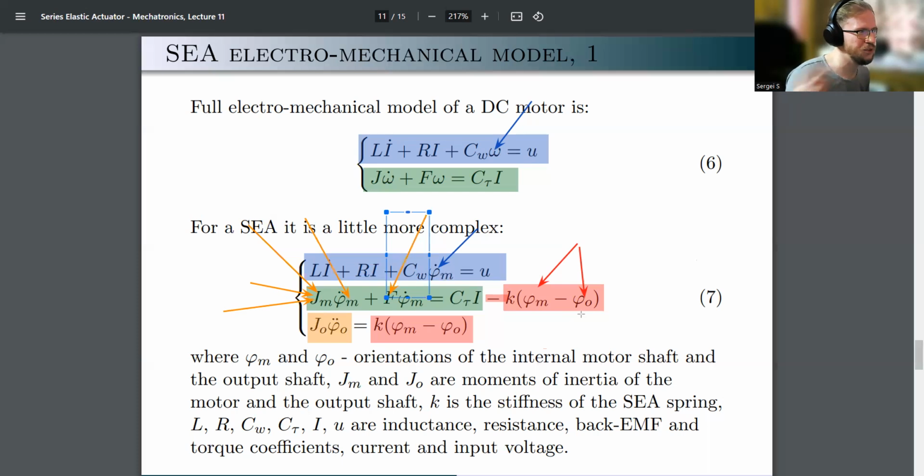So coefficients there would be small. But if you change variables and compute all of this in terms of rotation of the output of your gearbox, so that all of your angles are in terms of the output angle of the gearbox, the same angle that comes into the torsional spring, then those will be significant numbers. So you cannot ignore either of them.